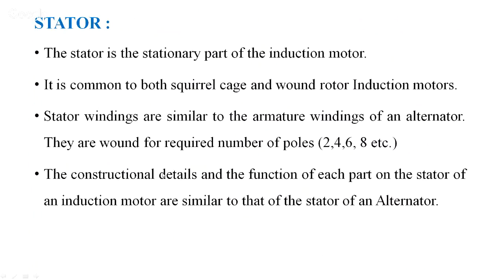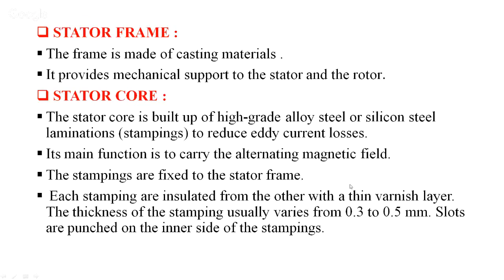Now the constructional details and the function of each part of the stator of an induction motor are similar to that of the stator of an alternator. We have already studied alternators or AC generators. So the construction is very much similar here also. The stator frame is made up of casting materials. It provides mechanical support to the stator and the rotor.